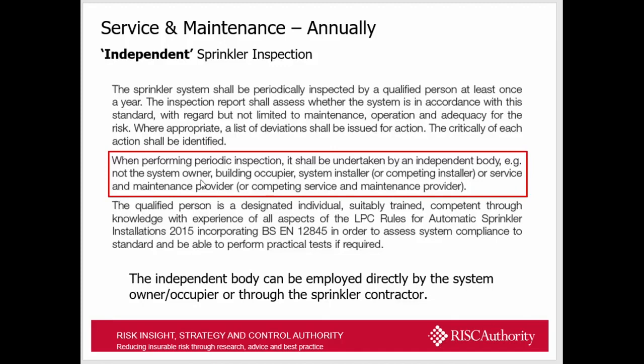And as highlighted in the box there, when performing a periodic inspection, it shall be undertaken by an independent body. In other words, sprinkler contractors cannot undertake this service requirement. And the reason why is that the industry would not like to have sprinkler contractors marking their own homework, or that of others, for their own gains. So that's why it's classed as an independent inspection. And on top of that, the qualified person is a designated individual who's got suitable training and is competent with knowledge and experience of the system, and shall be able to perform practical tests if required.